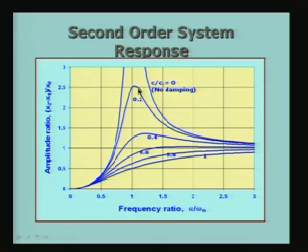As the damping ratio is increased, so I have plotted for 0.2, 0.4, 0.6, 0.8 and 1, you see that the amplitude becomes more manageable. For example, if the value of the damping ratio c by cc is greater than 0.6, the response is never greater than 1, it is always below 1. That means that the amplitude ratio is reduced to a value less than or equal to 1. You also will notice that the amplitude ratio varies quite significantly for omega less than omega n, and it grows in size, and for large values of omega by omega n, that is for large values of the input frequency compared to the natural frequency of the system, the value more or less tends to 1. So, we can easily see that. In the next sketch I have actually done that.